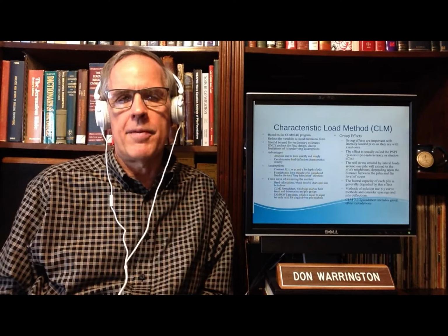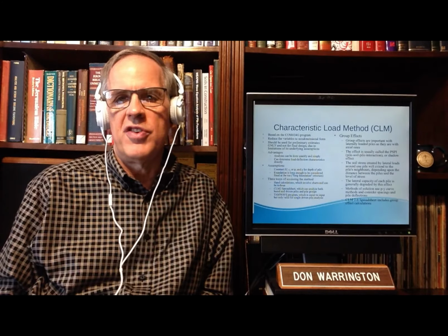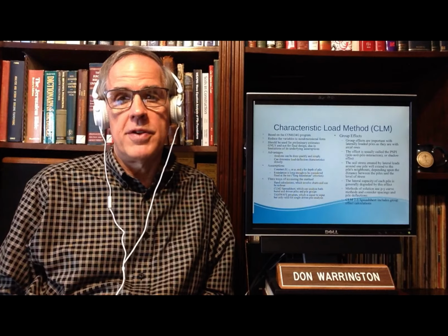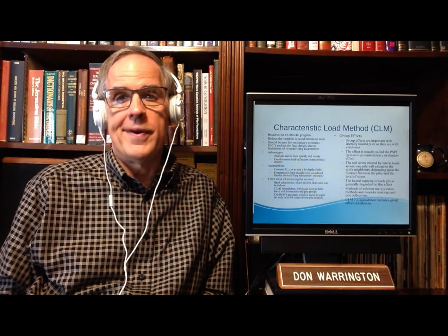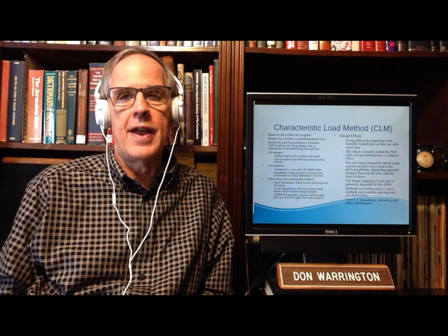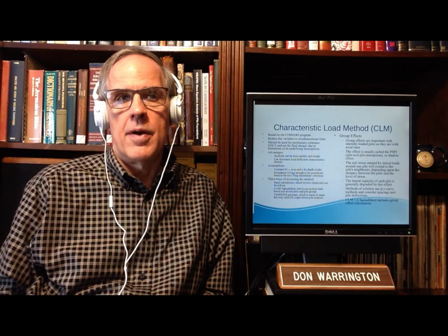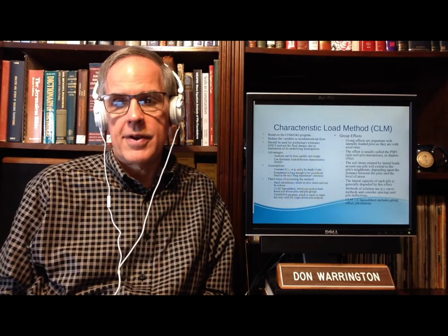Let's just forget about piles that are not rigid. Particularly with seismic, the flexibility of the pile is the whole point of using a laterally loaded pile. If I had to throw one out, I'd rather throw the rigid one out than the flexible one. And in fact, it's easier.